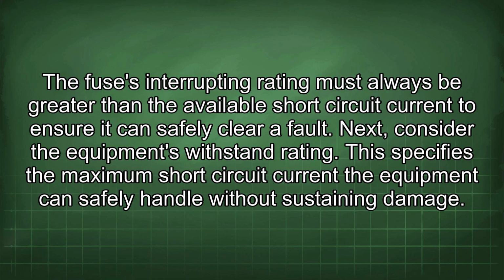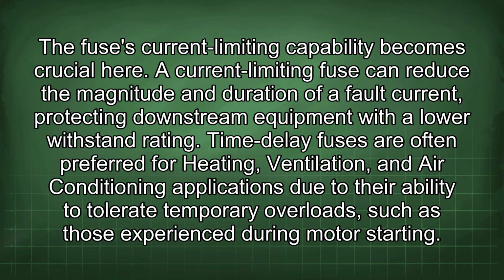Next, consider the equipment's withstand rating. This specifies the maximum short-circuit current the equipment can safely handle without sustaining damage. The fuse's current limiting capability becomes crucial here. A current-limiting fuse can reduce the magnitude and duration of a fault current, protecting downstream equipment with a lower withstand rating.